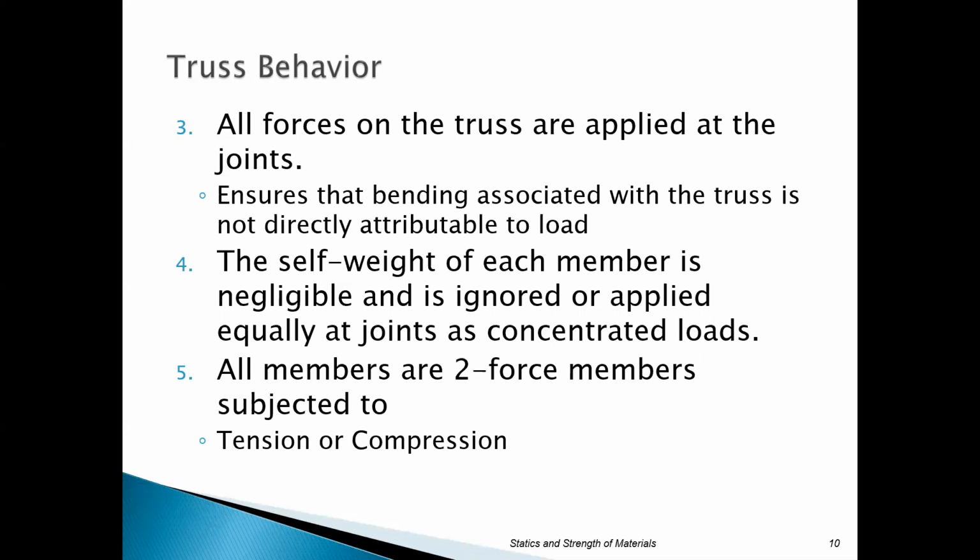So here's what you think about this: an I-beam that's 20 feet of any size is going to be really, really heavy. So what we're saying is that I-beam, or whatever type of big metal member that you're using, has no weight essentially, but it has been modeled into the external loads, because the external loads that we deal with are going to be so much heavier as opposed to what the structure is itself. Okay, so we ignore that. Self-weight's ignored.